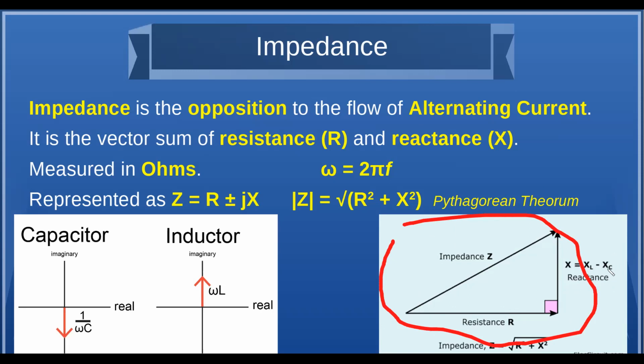So if you plug the negative in there, instead of the difference between the two, it would give you the sum. So it's going to be the difference between capacitive and inductive reactance. And I think that's what they tried to represent, but it really should have been plus X sub C.